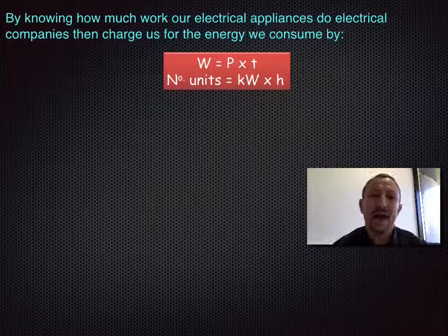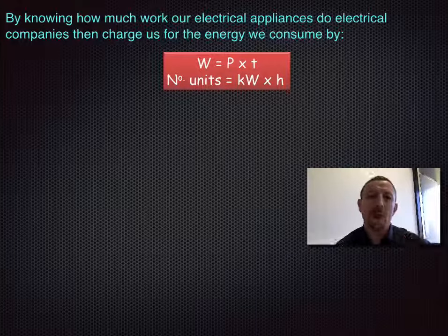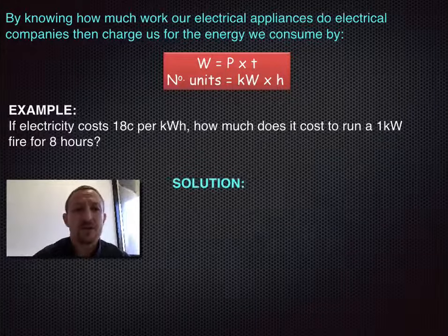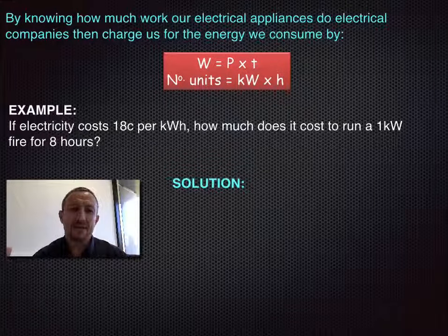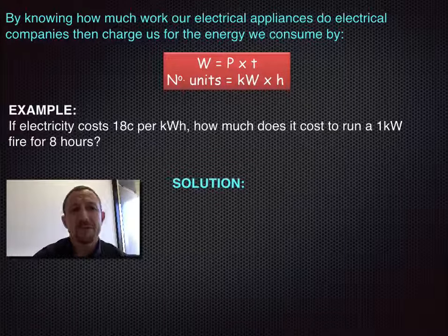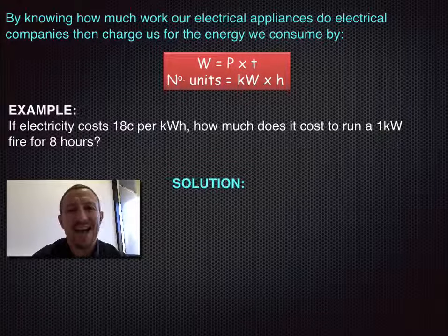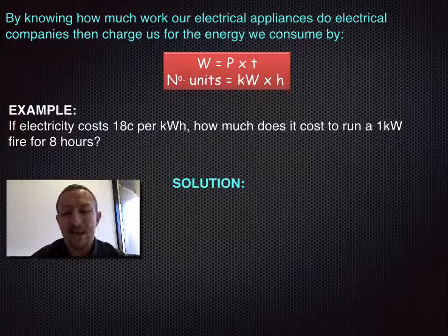So you may have to pay 80 cents, for example, for 1 kilowatt hour. So obviously the more kilowatt hours you utilize at home, the more you are charged. So here's an example where we can utilize cost and amount of power that we utilize as it goes through our house. So if electricity costs 18 cents per kilowatt hour, how much does it cost to run a 1 kilowatt fire for 8 hours?